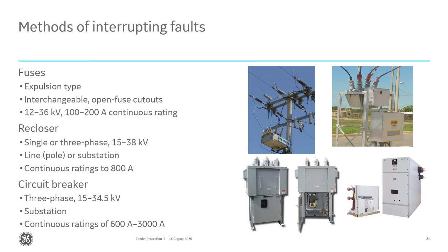And you have the circuit breaker. So you might ask, if I can have a pad mount recloser at the substation, why do I need the circuit breaker? Capabilities. The reclosers, as you can see with some of the ratings, are only rated for a certain continuous rating. And breakers are more robust pieces of equipment. They can have a higher continuous rating. And most importantly is the short circuit interrupting capability. The circuit breaker has a much higher short circuit interrupting capability than a recloser.